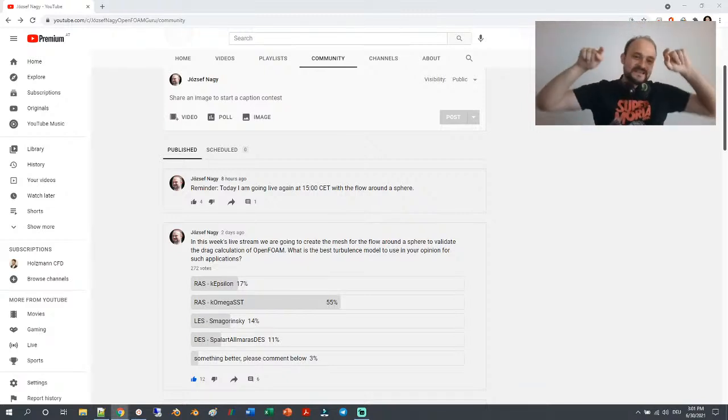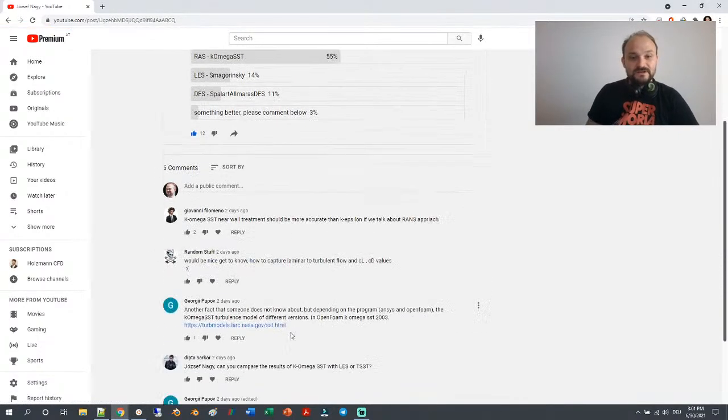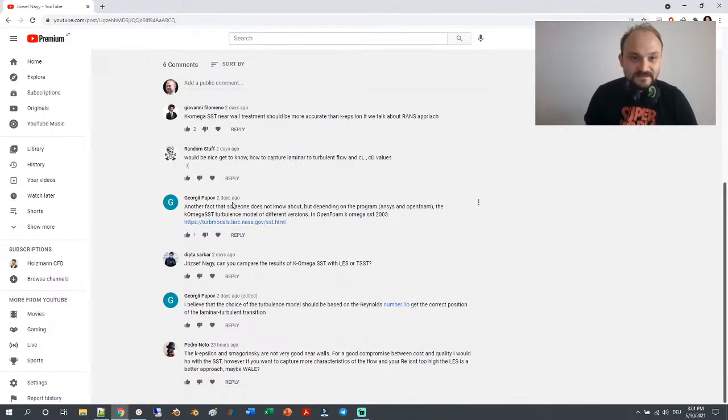So for this I posted on Monday a poll on YouTube asking what you think would be the best turbulence model to calculate the drag around a sphere, and as you can see here the poll is very clear. You think that the K omega SST model is the best suited, at least among the four that I showed you here. K omega SST captures laminar to turbulent.